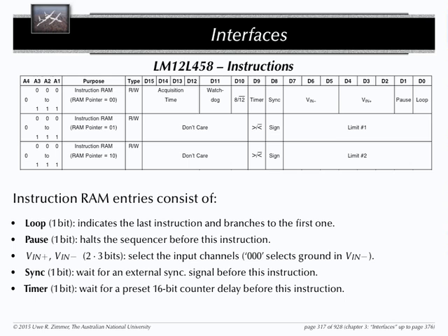Synchronization: wait for an external synchronization signal. That's interesting. AD converters often want to convert something which comes from the outside, right? So whether the signal is currently available is not necessarily clear. So maybe you want to convert a video signal, and when this video signal is actually available on my input lines is dependent on the sync signal, which is also some part of my video connector someplace. So I could use this sync signal on the video connector to trigger this AD converter to actually read the value in to convert it.